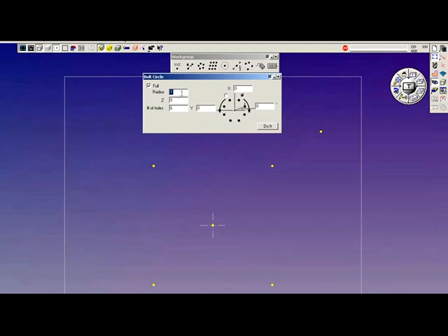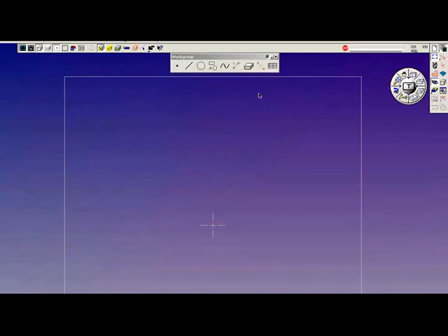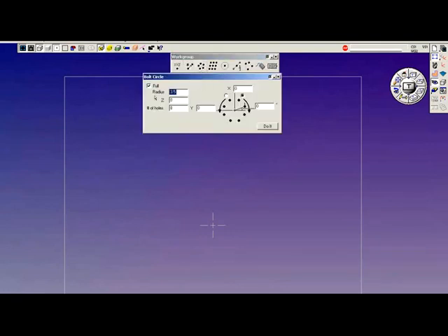Let's specify a radius of 3.5, Z0, and we're going to place 8 holes around this particular bolt circle. Now, the center of the bolt circle is specified by the X and the Y values. And I'm just going to make a quick new work group for this bolt circle here. Come back to my point, bolt circle, and my settings are retained.